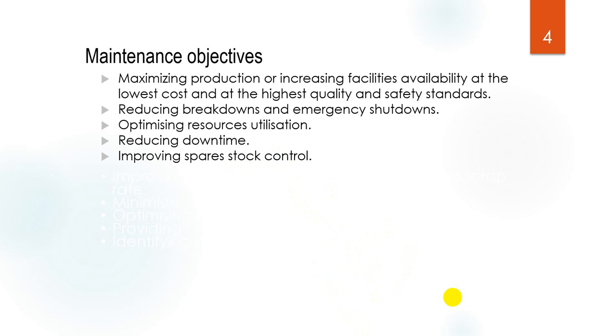There is a very important part when considering maintenance, if you're doing PM or the preventive maintenance concept. What does that mean? That means you are doing certain maintenance activities for a certain period of time, right? That means you need spare parts and different resources, and these resources should be repeated every certain time. That means you need stock of these spare parts, for example. If you follow this kind of philosophy, that means you need a big stock in your store to cover this PM program, the preventive program.